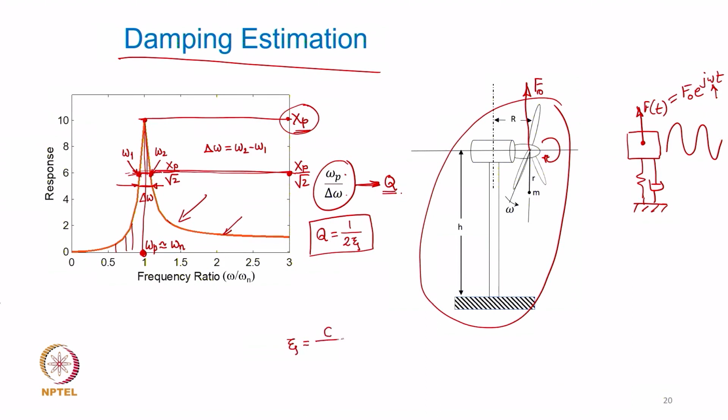You need to know what the actual damping in your system is, and Cc, that is the damping factor. Now, if I ask you to find out the damping factor for your system, you will first figure out the quantification of this damping coefficient. You never know, in a vibratory system like this, if there is no dashpot, where that C is coming from, right.